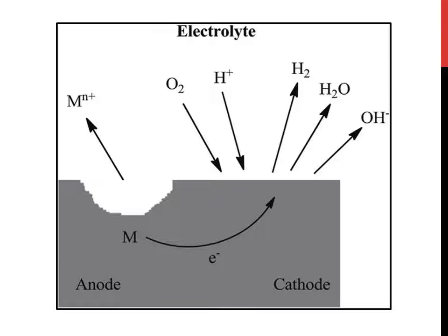So, this is the basic principle behind the corrosion process for all the metals, and this same electrochemical theory can be effectively applied to explain the formation of rust. So, we know how a metal is corroded and how we can apply this same principle in explaining rust in the case of the destruction of iron. That is, rust is nothing but a formation of oxides of iron, that is the ferric oxide or hydrated form of ferric oxide.